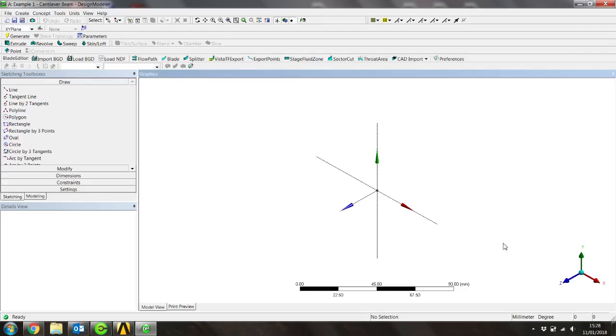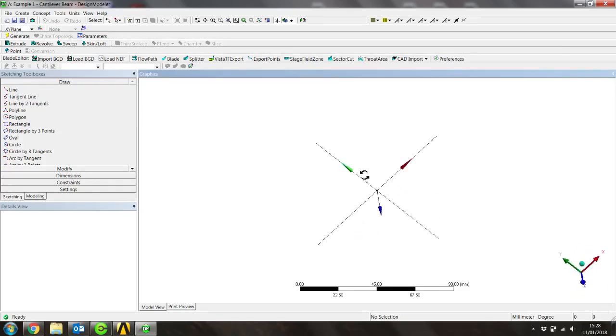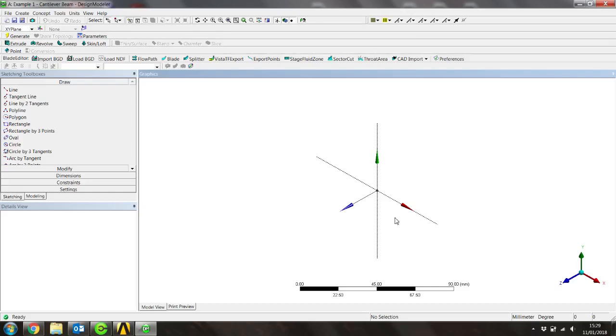So next thing to be aware of, the little XYZ axis controller in the bottom right corner here. This will help you zoom and pan around the geometry that you draw. You can simply hold down the scroll wheel or the middle mouse button and drag this around to get a 3-dimensional view, or you can use the controllers here. So if I want to look in isometric orientation, click on the light blue dot. If I want to look at the XY plane, I can click on the Z axis and it will automatically zoom into 2 dimensions there.